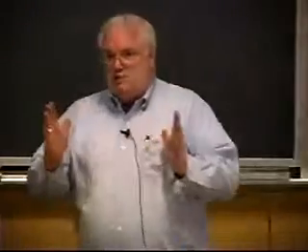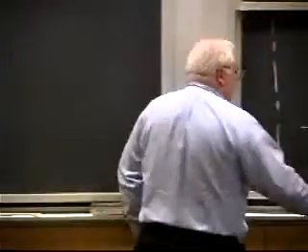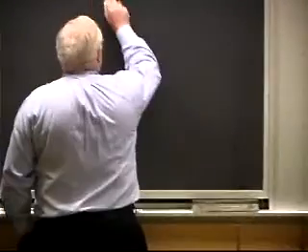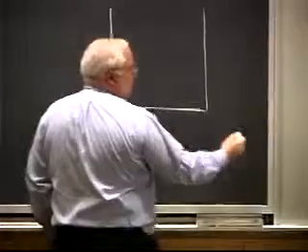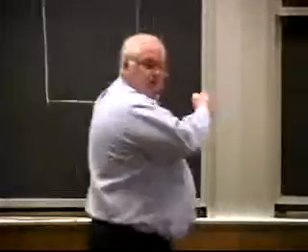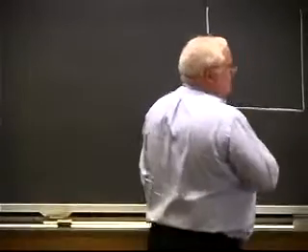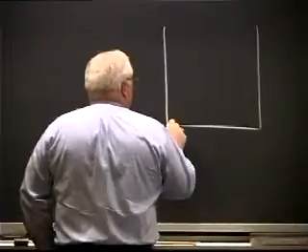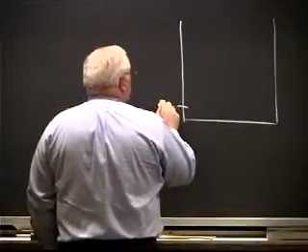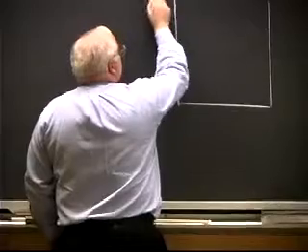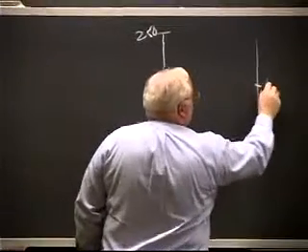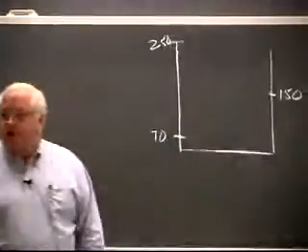Now this is a simple linear heat flow. And what they've told me is one guy, the welder, claims he left it, and I don't know if it's exactly 12 hours or what, but he left it and there's no heat flow this way because this is the mirror plane. There's another beam, another part of the box beam on the other side. So there's only heat flow out this way. Now, if this is room temperature, which back in August was 70 degrees, 80 degrees at night, and this is 250 degrees, and the guy claims when he came back in it was 150 the next morning.